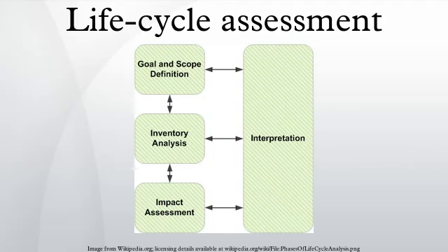Cradle-to-cradle or closed-loop production. Cradle-to-cradle is a specific kind of cradle-to-grave assessment, where the end-of-life disposal step for the product is a recycling process. It is a method used to minimize the environmental impact of products by employing sustainable production, operation, and disposal practices and aims to incorporate social responsibility into product development. From the recycling process originate new, identical products, or different products. Allocation of burden for products in open-loop production systems presents considerable challenges for LCA. Various methods, such as the avoided burden approach, have been proposed to deal with the issues involved.